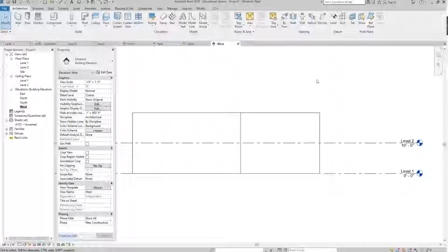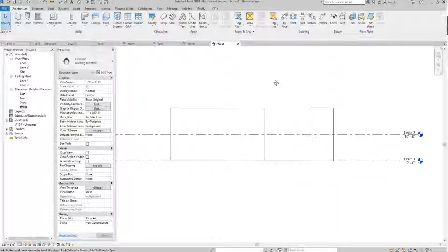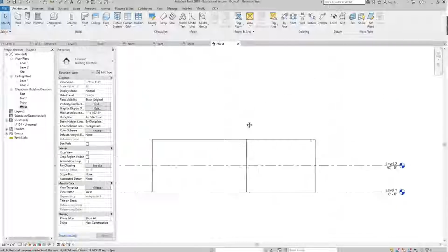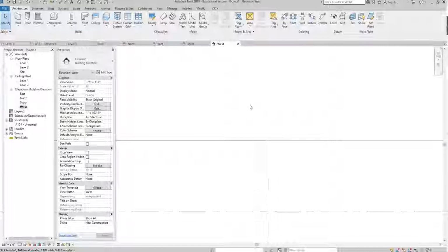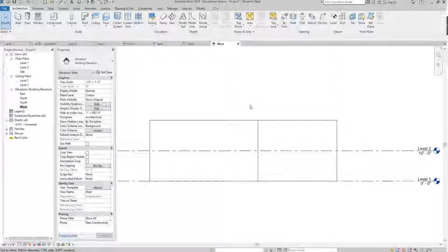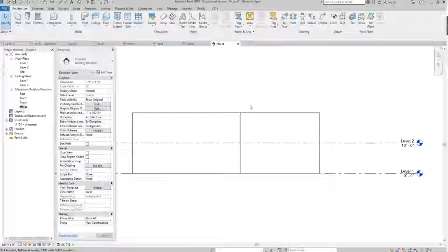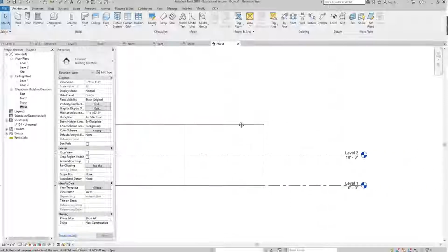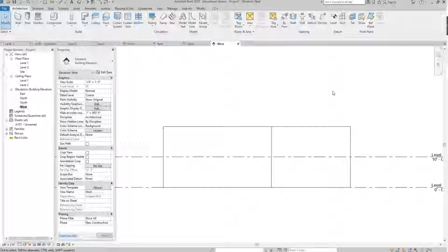Okay. I can also pan in my drawing space. To pan means to move your drawing across your drawing space. If I hold my middle roller button down and I move my mouse, this is panning. Okay, so I zoom in, I zoom out, I double click my roller twice very quickly to zoom extents, and then I can pan. All right, and I want to remind you, you hit escape a few times to clear out any command you're in, whether it's a zoom, a drawing command, whatever it is. Escape clears me out of my command.